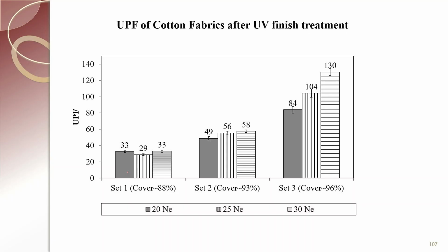The UPF value initially at low set dropped and then increased, but at higher cover factor, interestingly, which is different from polyester, here it is consistently increasing from the coarser yarn to finer yarn.